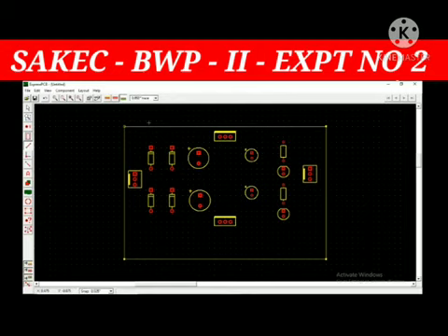According to your ampere requirement you can change your track width. We are using now 0.05 inch, which is equal to 2.5 mm. This layout is for 2 ampere, so you have to select this layout. And third, try to avoid 90-degree angle. But for a low power supply you can use 90 degree also. So these are only three rules.